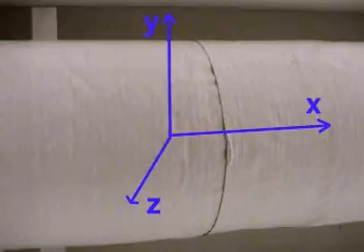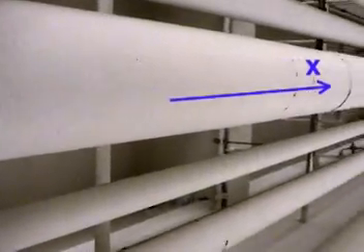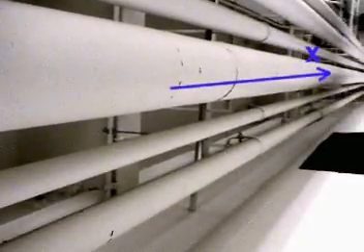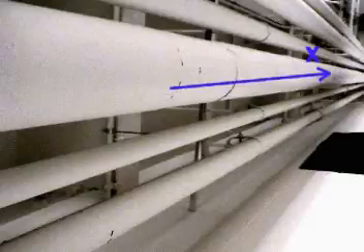For example, the flow through a pipe has 3 space dimensions x, y, and z, but often we're mainly interested in what changes along the pipe. Many pipes are so long compared to their diameter that we can neglect the change of parameters across the flow and consider only what changes with length of the pipe in the x direction. This is a one-dimensional flow approximation.